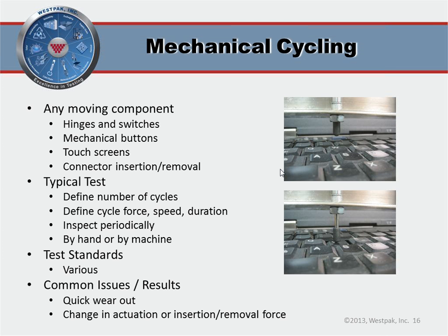The laptop's a very good example, but also think about, you're designing a chair. You make an analog for someone sitting in it or getting back up, or a pillow, someone putting their head on it, releasing it. This can apply to just about anything. It's just life cycle testing. The last thing on life cycle testing is usually this is done at room temperature, just out of convenience, but think about doing this at elevated or cold temperatures because especially plastic products will act very differently.